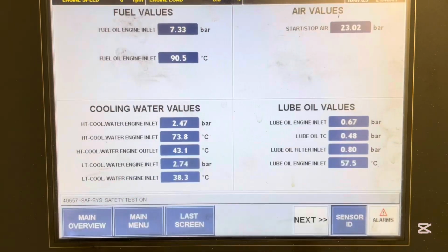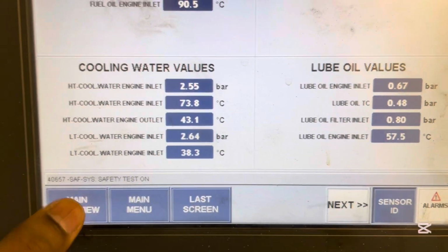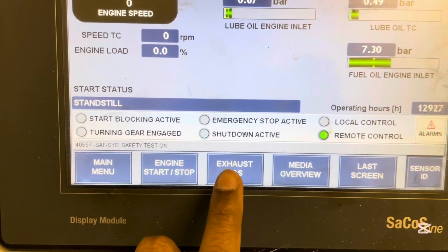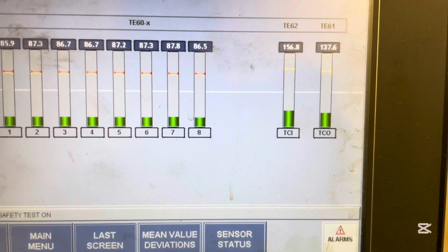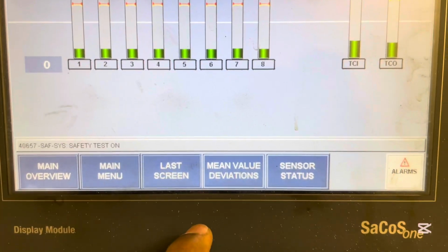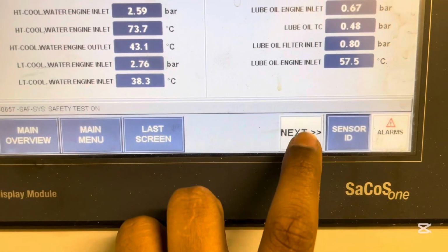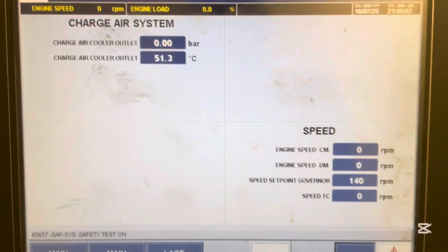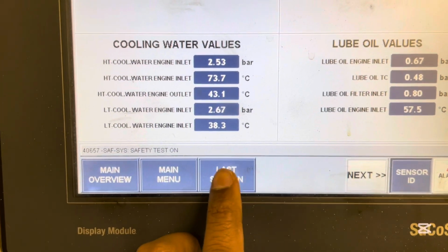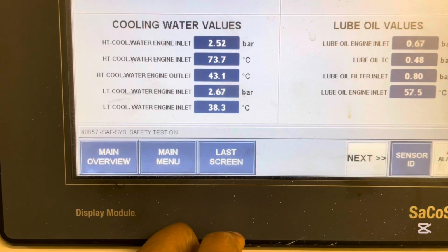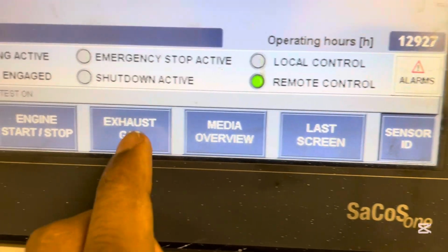So basically this HMI will communicate with the control module that is present inside this particular control panel, which in turn communicates with the other three remote control areas present in the engine control room via digital signals, which carry the binary codes 0 and 1. And other than that, the control module inside this engine control system also receives analog signals from the sensors and transmitters that are used to monitor safety parameters. So they use the analog signal.